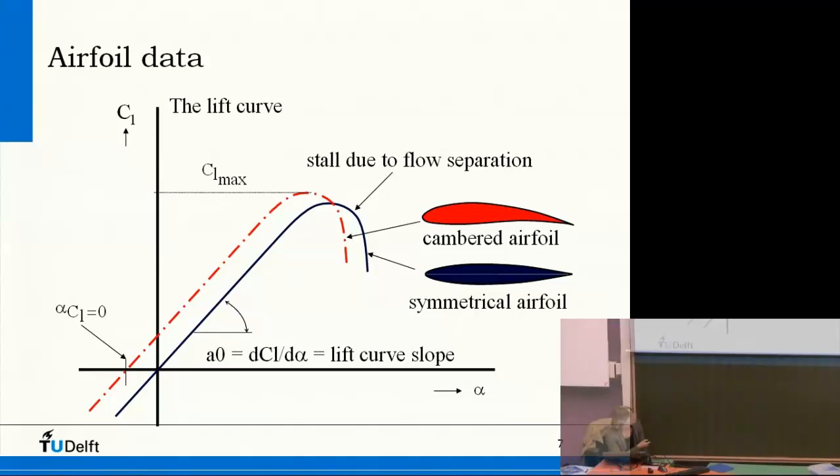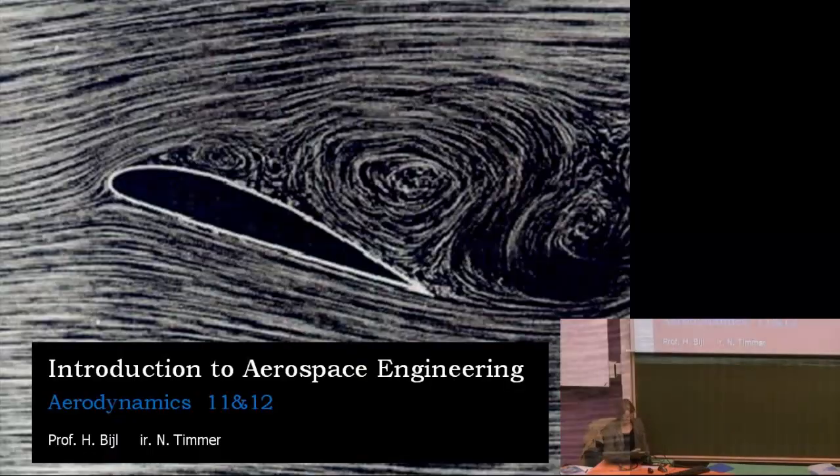It usually starts somewhere close to the trailing edge with a small bubble because you get separation. Sometimes laminar flow separation, the flow becomes turbulent and reattaches, so you get a small separation zone. But if you increase the angle of attack, the separation will become larger, larger, larger, and at some point you will have leading edge separation. So really separation at leading edge, and that is this picture. So this is a picture of really separation.